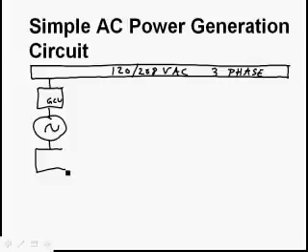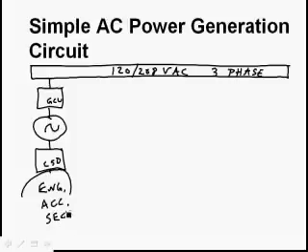So going into it, we're going to have a generator control unit, and before that is going to be our AC generator, and driving that is going to be our constant speed drive, and of course that is going to be hooked on to our engine accessory section.